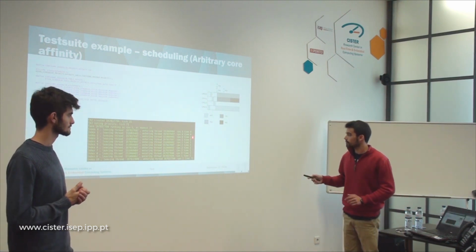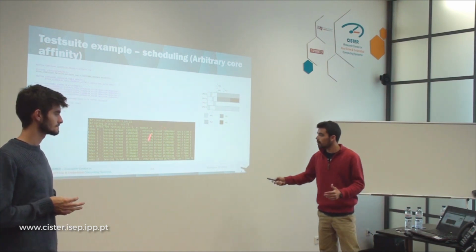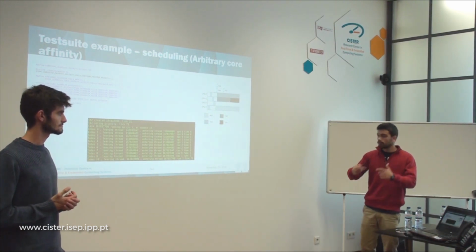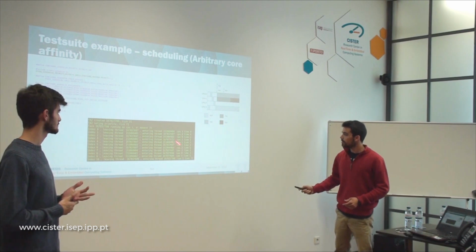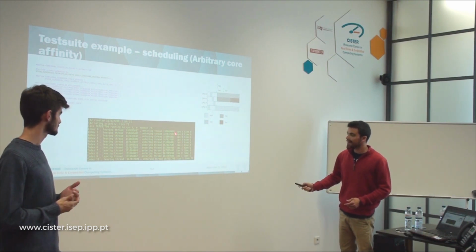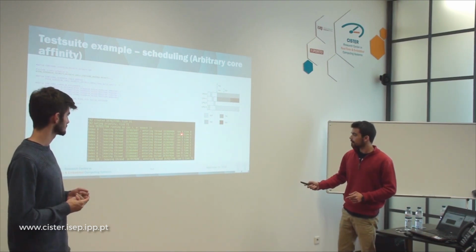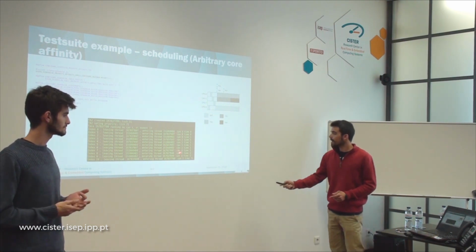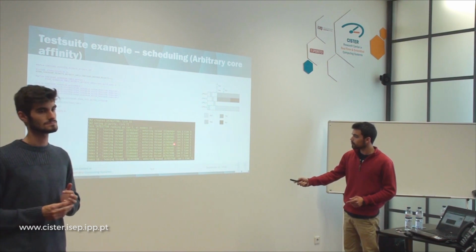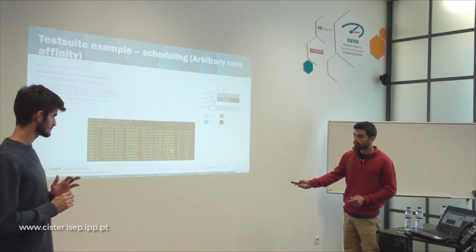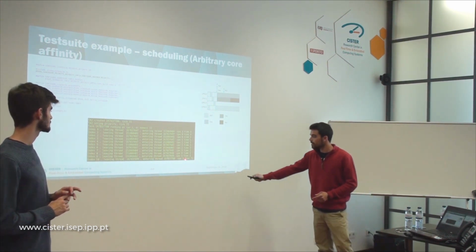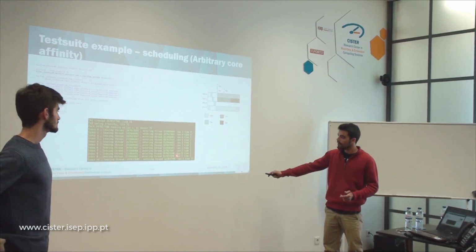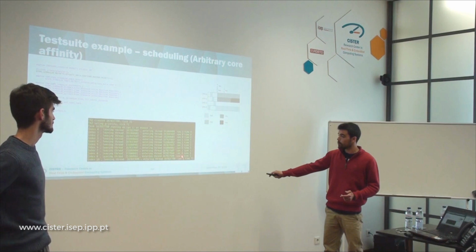And here we have what I just described, our results, to compare with our scheduling diagram to verify if it is correct. As you can see here, the 97 is the init task that is moved to CPU 0, then here to CPU 1, here to CPU 2, and here finally back to CPU 3. Then we create the tasks TA0 and TA1 that enter CPU 0 and CPU 1.